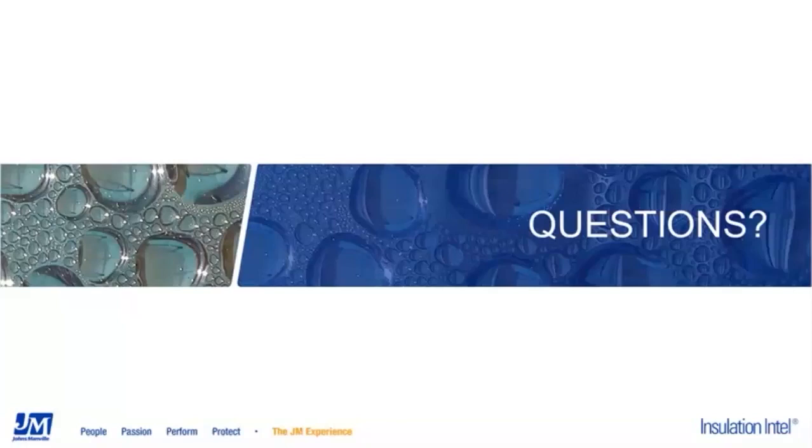That's a tough one. I think you work closely with your contractor to figure out how to maintain your vapor retarder integrity or continuity across that. The problem is that the pipe may expand and contract, the insulation might move, and you need to have a way to maintain that vapor retarder continuity even in light of the pipe and insulation moving.